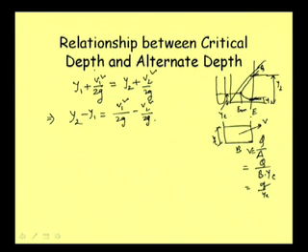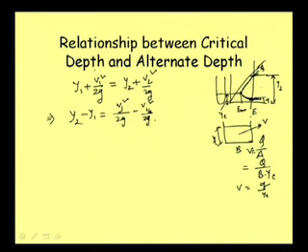Whatever the velocity may be, here the velocity is v1, and in the second section, where the depth is higher, the velocity is v2. Definitely v2 will be less than v1, but the unit discharge is not changing. We are talking about this specific energy line for a given discharge, and when the discharge is the same and it is a prismatic channel, B is also the same, so the small q is not changing.